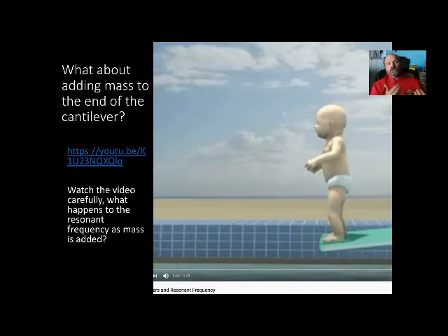This is really good to do with micro-cantilevers if you're looking for a certain, say, virus, or a certain bacteria or a certain chemical. You can coat the cantilever with something that only that chemical or virus sticks to, like a certain antibody. And then if the virus comes by and sticks to the cantilever, the resonant frequency of the cantilever will shift. As a result of that shift, you can tell, one, that you detected the virus, and two, by the amount of the shift, you know how much virus you've detected.